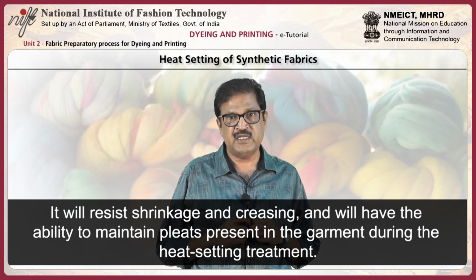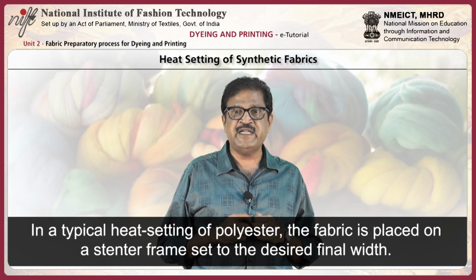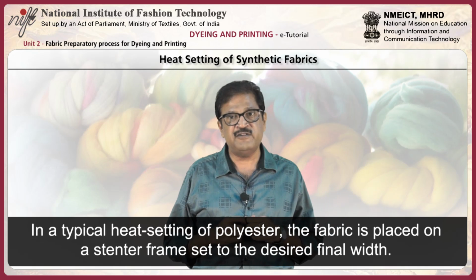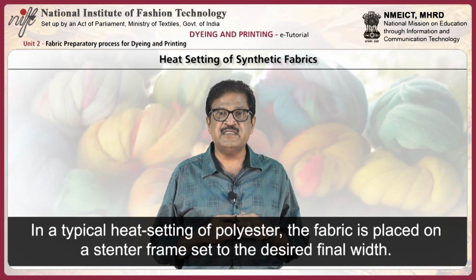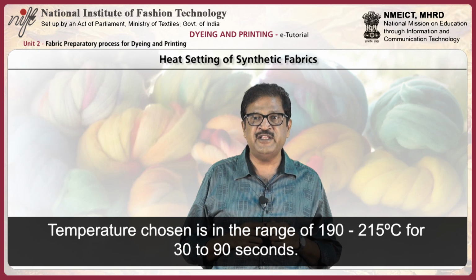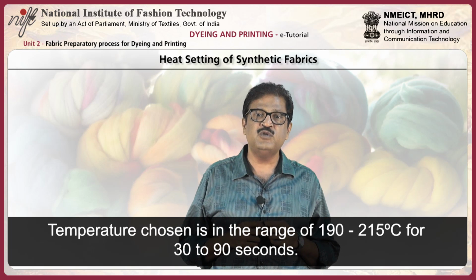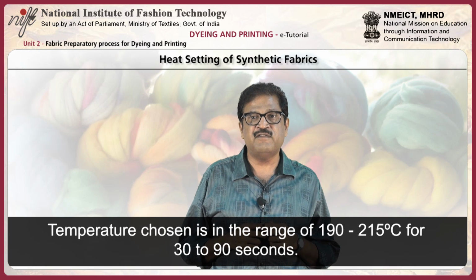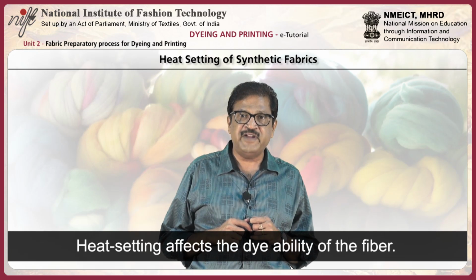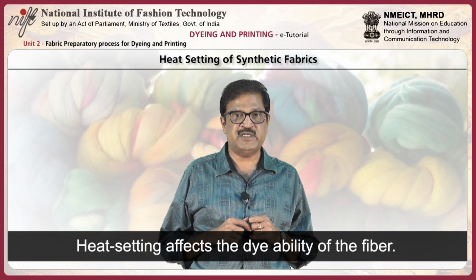It will resist shrinkage and creasing and will have the ability to maintain pleats present in the garment during the heat setting treatment. In a typical heat setting of polyester, the fabric is placed on a stenter frame set to the desired final width. The temperature is maintained in the range of 190 to 215 degrees Celsius for 30 to 90 seconds. Heat setting affects the dyeability of the fiber.